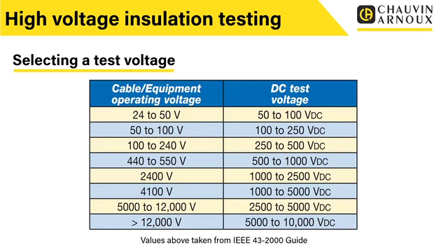And we'll also talk about, as we go on, step voltage testing. Step voltage testing, again, uses that difference in test voltage, that increased test voltage, to actually tell us about the condition of the insulation. So depending on the application you're working on, depending on the actual type of equipment and its rating, that's where we would look to see what would be a suitable test voltage.